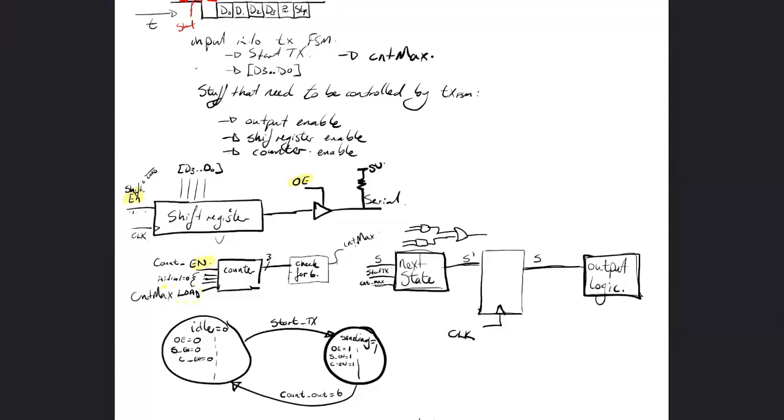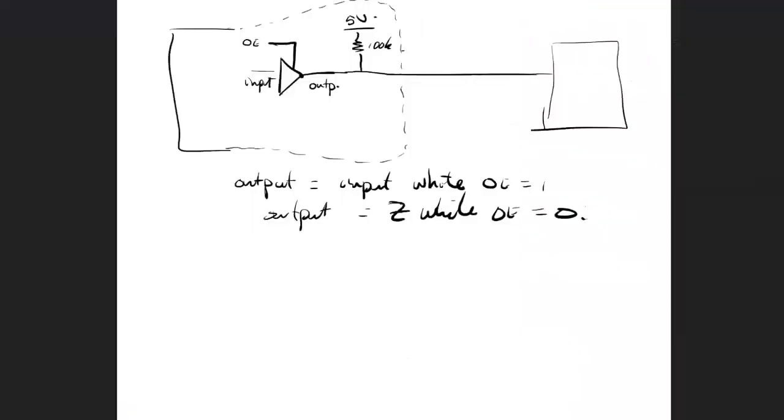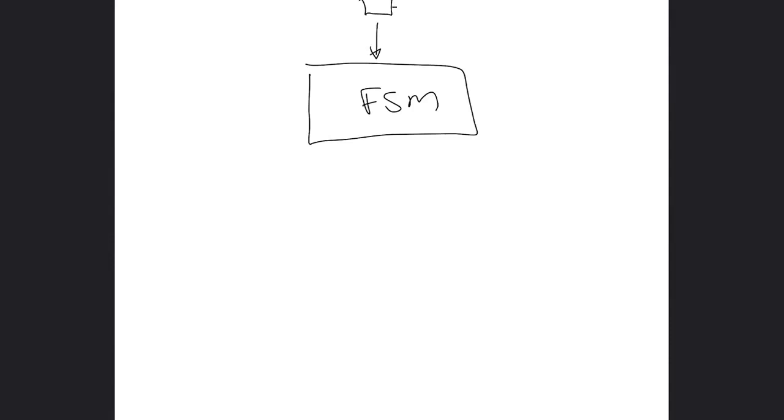Okay, so the first thing I wanted to say, just because many people are struggling with it, is that it's very important that you treat the components in your state machine as separate components. So for the transmitter, for example, you want to have the counter completely separate from the rest. I just want to show you what I mean there. For your transmitter state machine, you will have a transmitter FSM, and obviously inside this FSM is a flip-flop that remembers the state.